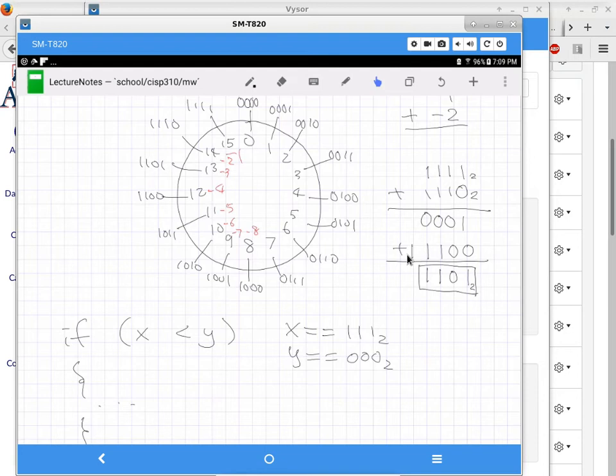Yep. Back there. What happens if you put that to a 5-bit adder? So that addition, what if you perform that calculation on a 5-bit adder? The carry would then become part of the sum. But then it will also have its own carry out. In other words, it doesn't matter how wide the adder is. There's always an extra carry bit to the most significant side to remember, basically, do we have an overall carry after this entire addition? Is that okay?